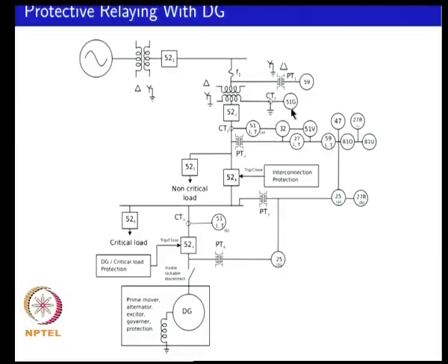So, another aspect that needs to be considered when you do such an interconnection is what should be the actual settings of the protection relay values. For example, in this 59 under voltage relay, the question might be what would be the neutral voltage setting that has to be included, or for example in the 51G what is the ground current level, what is the overcurrent level, and at what over frequency or under frequency would the decision be made to disconnect the device.